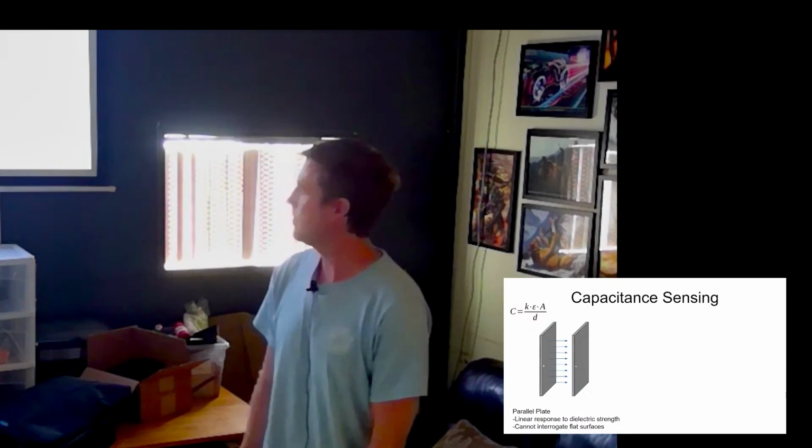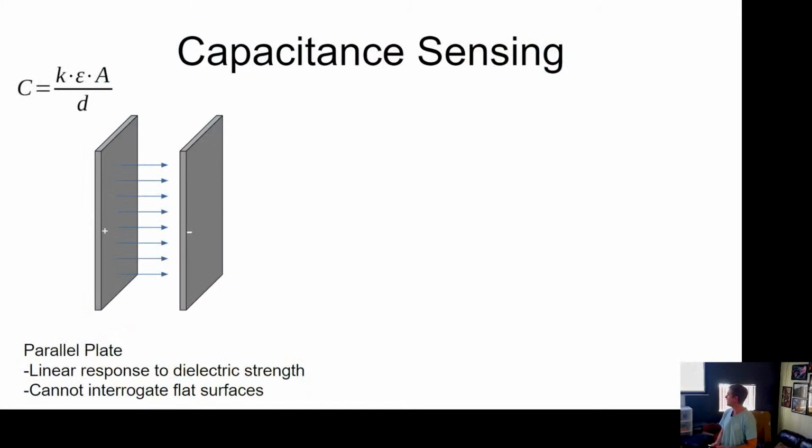A capacitor in its simplest form is just two conducting plates separated by some distance d. This separates these two conductive plates, so you have a charge on either one. The capacitance is proportional to the area of those plates divided by their distance separating them.